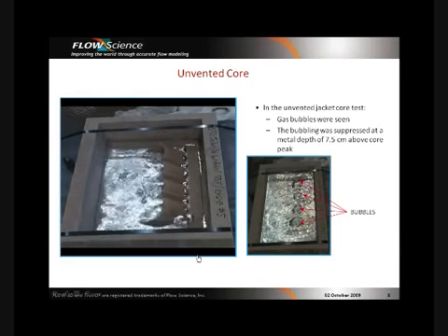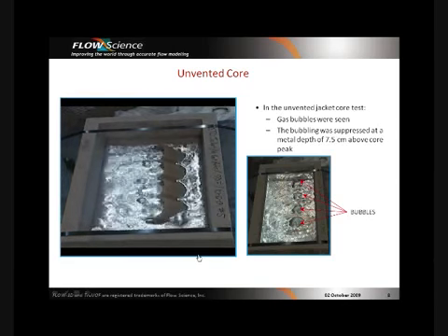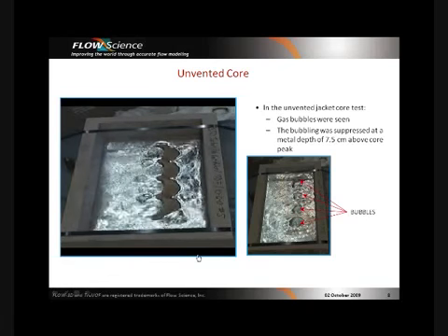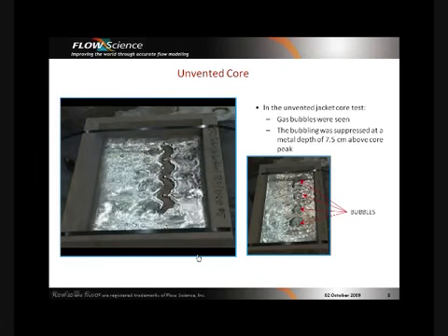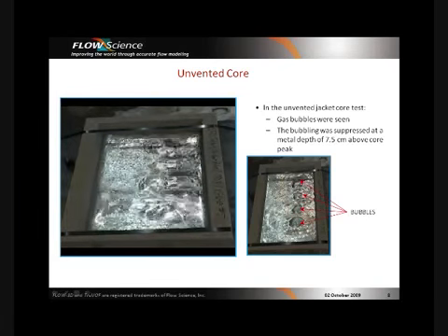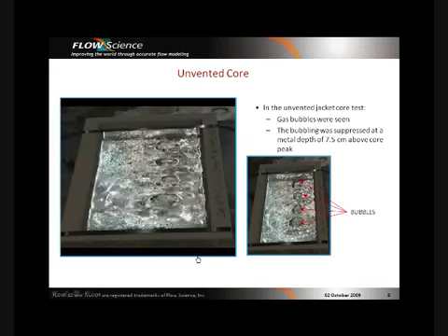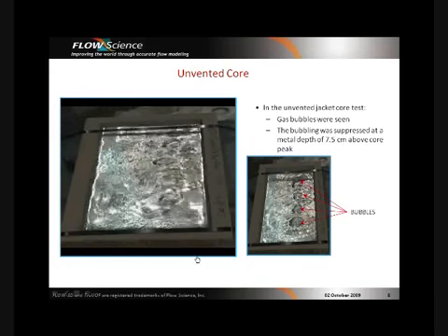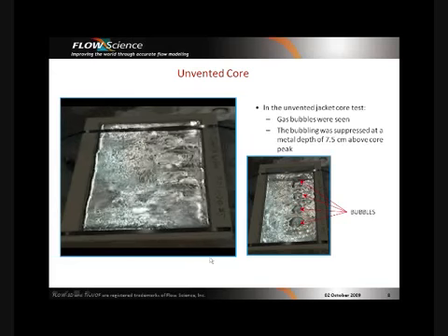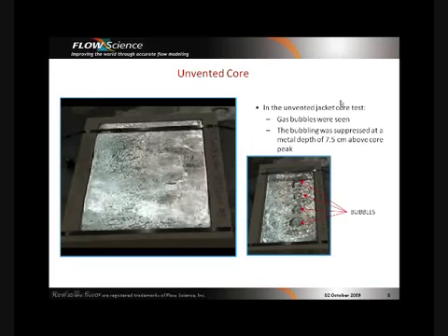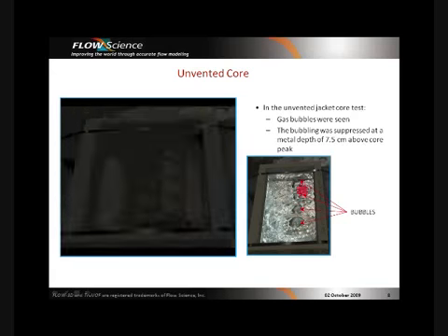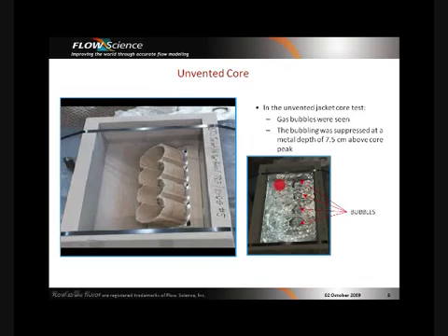This happens at about 8 seconds into the simulation, or into the video, and another row of bubbles is formed approximately 15 seconds from the beginning. All these bubbles are suppressed at a metal depth of 7.5 centimeters above the core peak. This image on the right-hand side points out the location for the second set of bubbles.